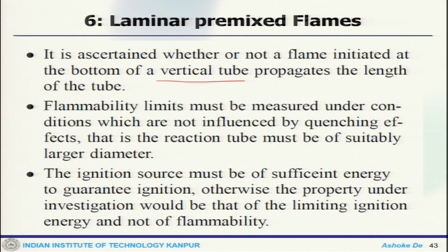And flammability limit can be measured under conditions which are not influenced by the quenching effect. That is, the reaction tube must be of suitably larger diameter, so that there is no quenching taking place. That means you are allowing a complete flame structure, and only then can you measure this limit: what is the lower bound and what is the upper bound where the flame extinction actually takes place. Now, the ignition source must be of sufficient energy to guarantee the ignition, otherwise the property under investigation would not be limiting the ignition energy.